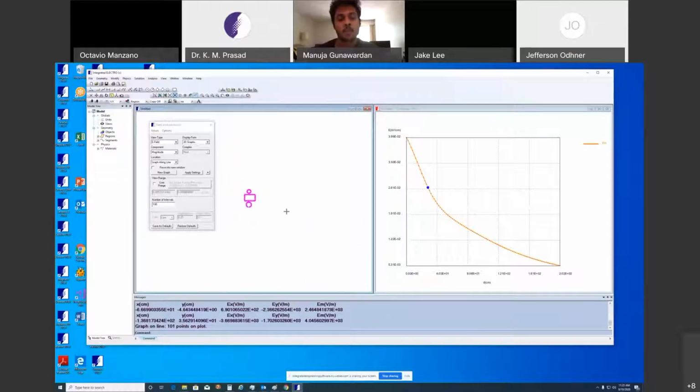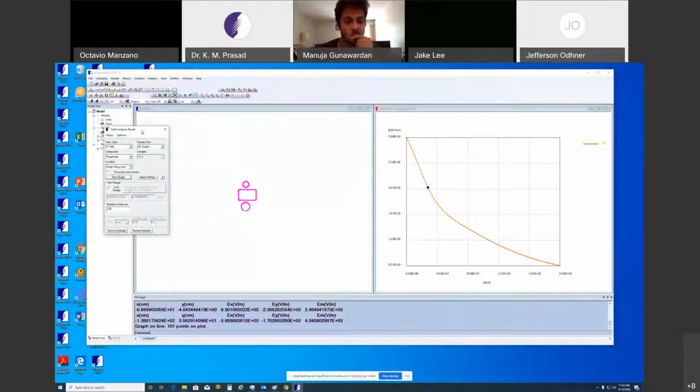Another point I mentioned here: because we are using the boundary element method, you can calculate the graph or the results anywhere. There is no limit because there is no artificial truncation of the region. Whereas in the finite element method, the problem is artificially truncated at approximately 5 times bigger than the model area. They put an artificial region. You can see the results only within that region, but not outside. In the boundary element method, you don't have that problem.